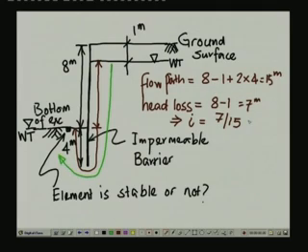that is equal to about 0.5, approximately equal to 0.5. Okay. Now you know that because of the flow taking place, you are going to have an upward seepage pressure in this case, and as I have indicated in the previous lesson, seepage pressure is going to be given by p equal to i times gamma w, that is equal to 0.5 times 9.81.